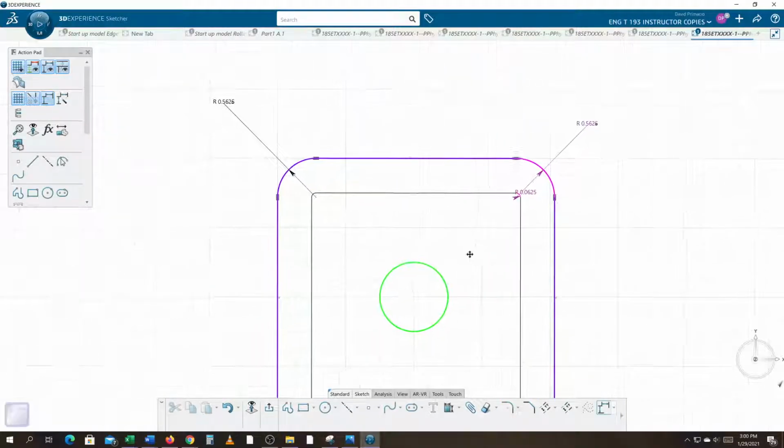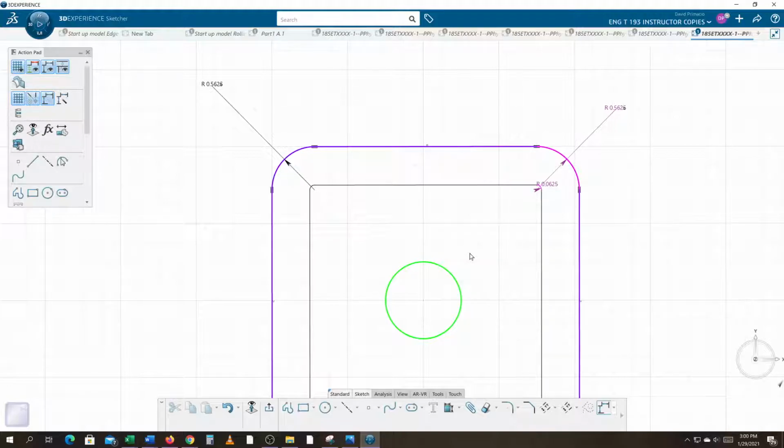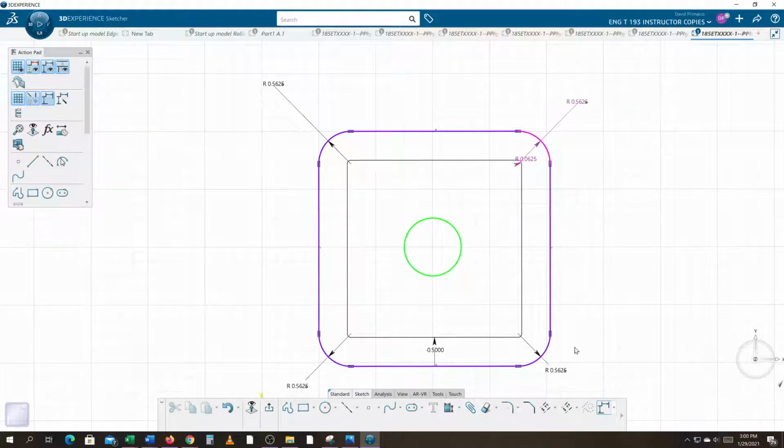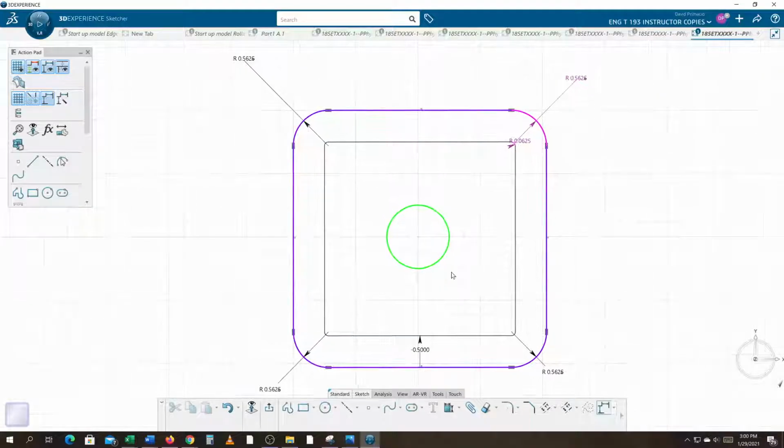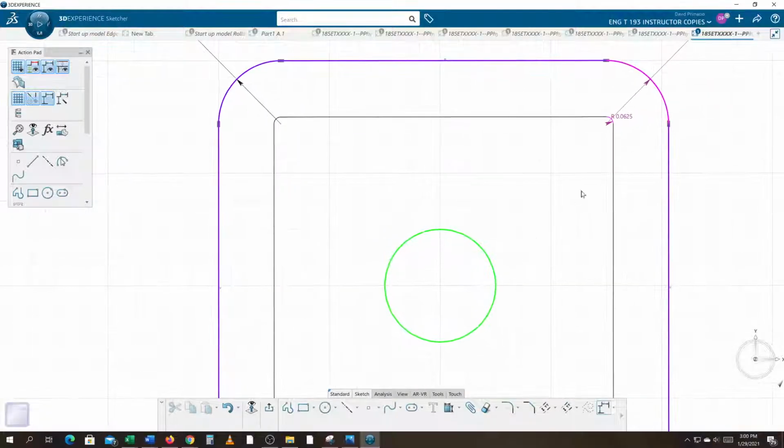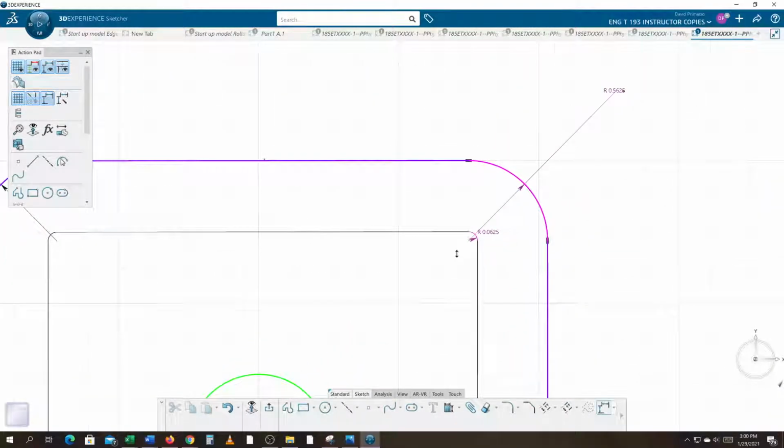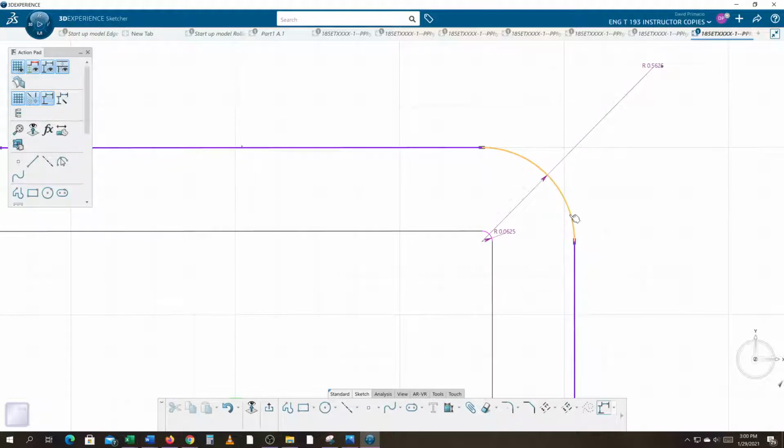You try and work to where the guys in the shop could use the most common tools that would be available, and your most common tools are 1/4 inch, 1/4, 1/8, 1/16, 1/32. Okay, so a 9/16 radius would have very little effect on how the engineering part is affected, and make it a lot easier to just go ahead and grab a bigger cutter to do that route. When I was in engineering, or when I was an NC programmer, if they gave me a 1/2 inch radius, I just bumped their radius to 0.53, knowing that I'm still within engineering tolerance.